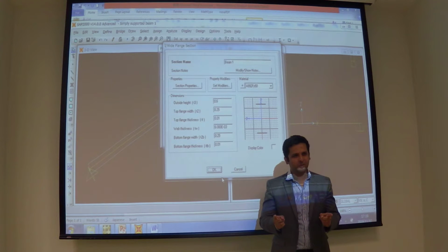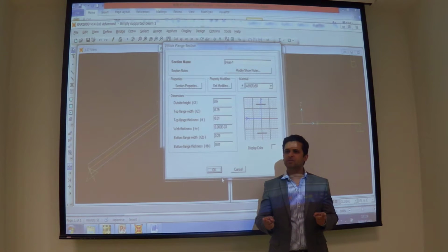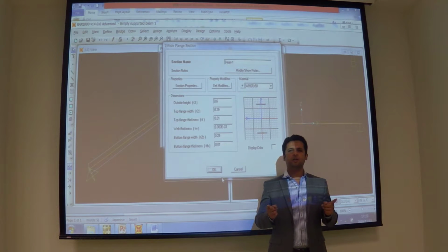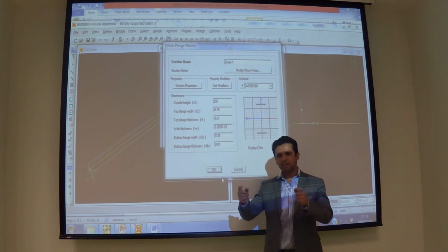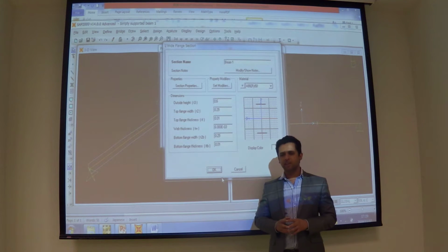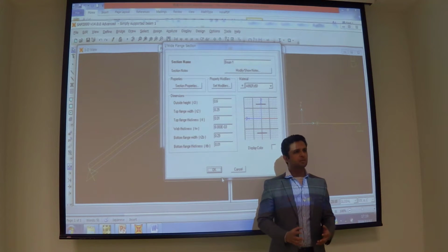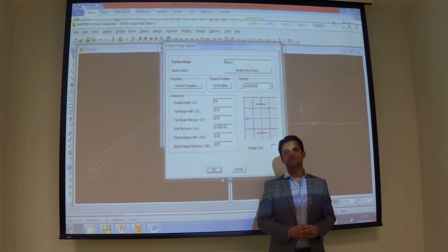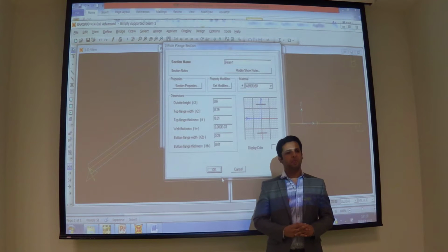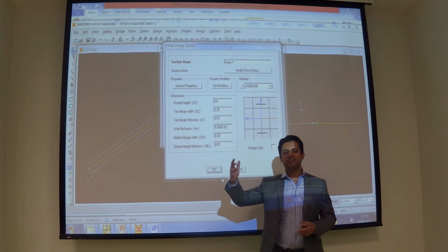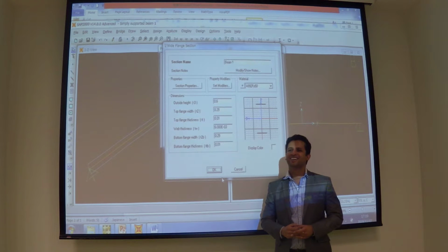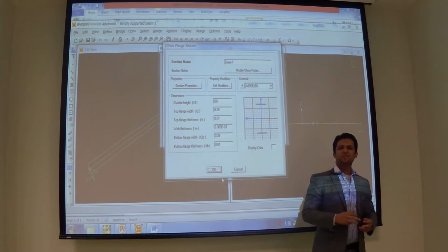Do you understand? What does it mean? It means that the required load is one fifth below the capacity. Why did this change happen in me? When I started as a designer, I kept it 0.8. But now, if I design something, I keep it like 0.999. Why? There's no big difference, it's more economic. But why was I not economical when I started? Safer. You were a beginner like us.